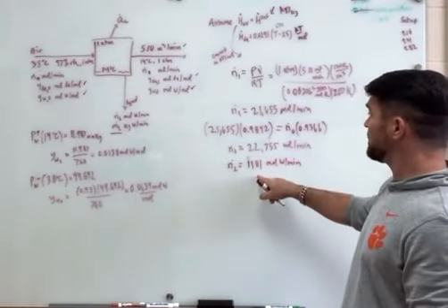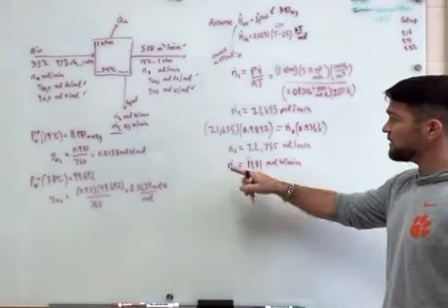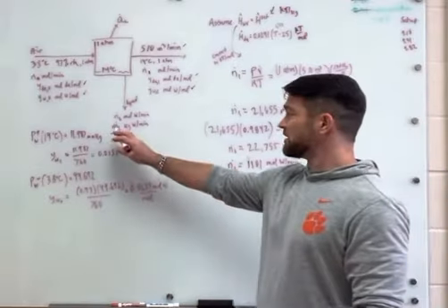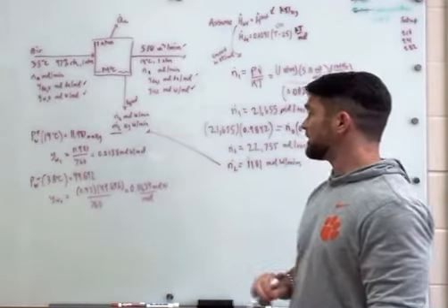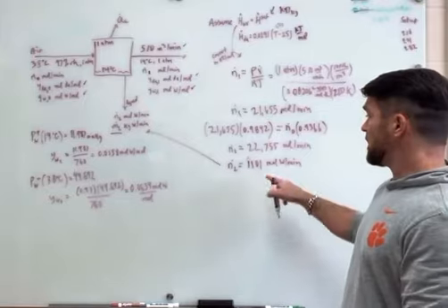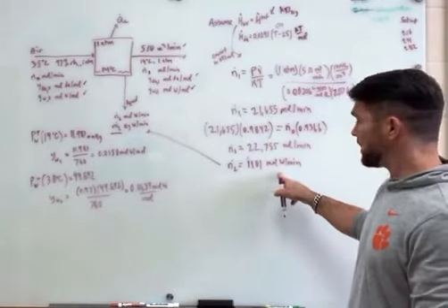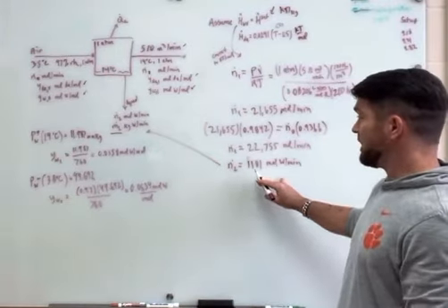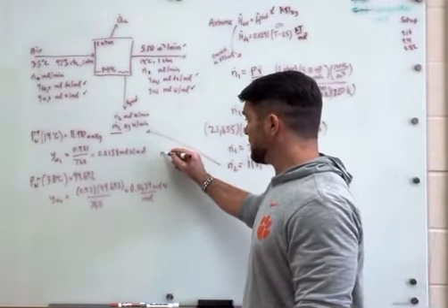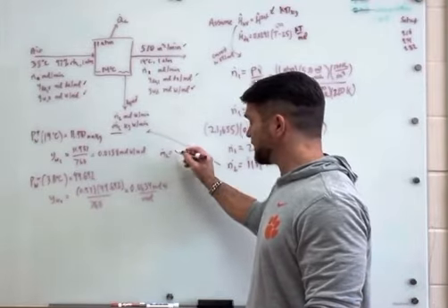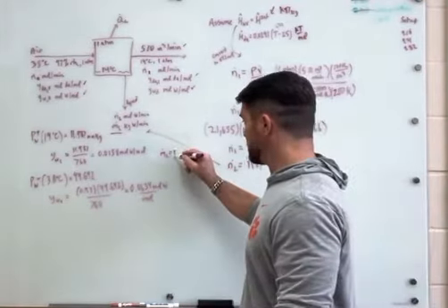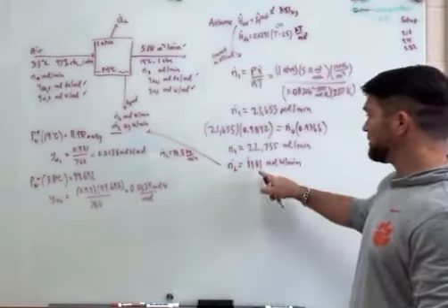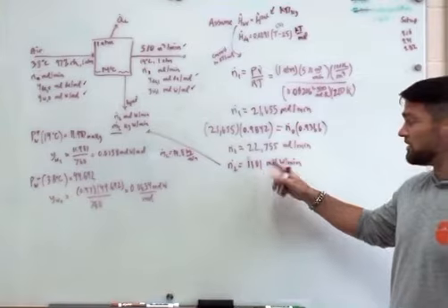We don't need to write down the other moles. We can just use that for now. The problem asks us to calculate this right here. To get it, I just have to use the molecular weight of water and also convert the units. If I do that, the mass flow of the liquid water is going to be 19.8 kilograms per minute. I multiply this by 18 grams per mole and then divide it by 1,000.